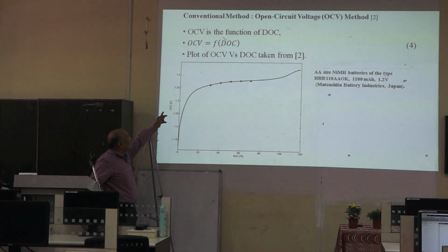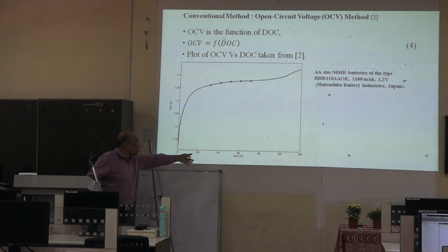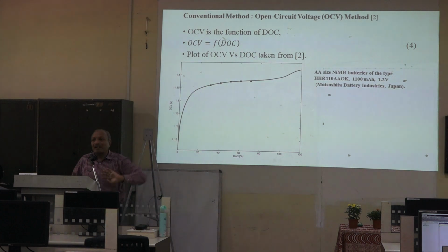That part, up to that 1.35, the open circuit voltage, whatever is there, that is the A0. That should be estimated, known, or given by the manufacturer. After A0, how much percentage we are going to find, here 20, 40, 60 or like that, as per the time T we are going to run; with respect to that, A1 comes.